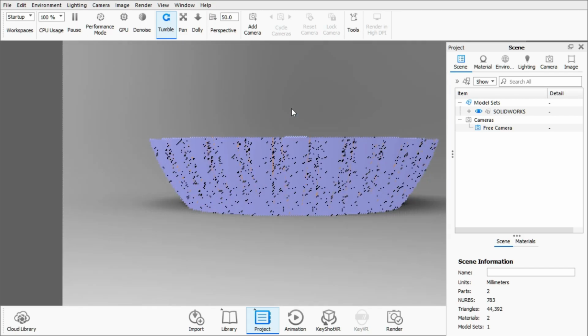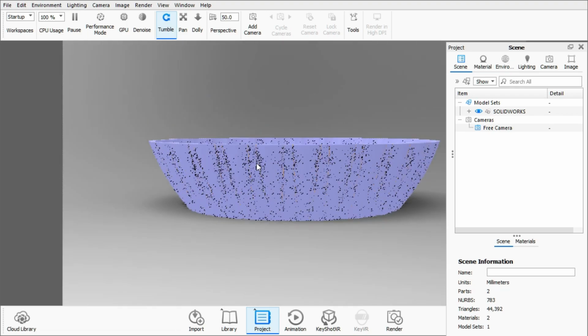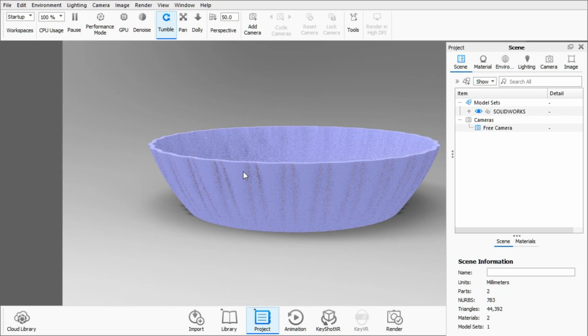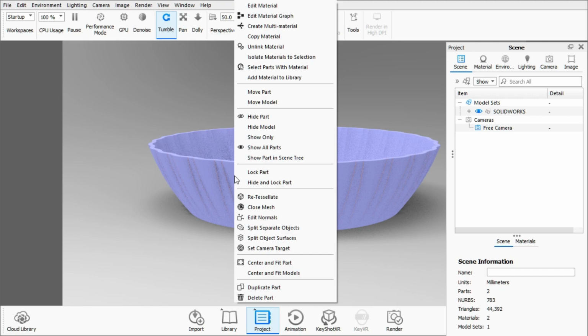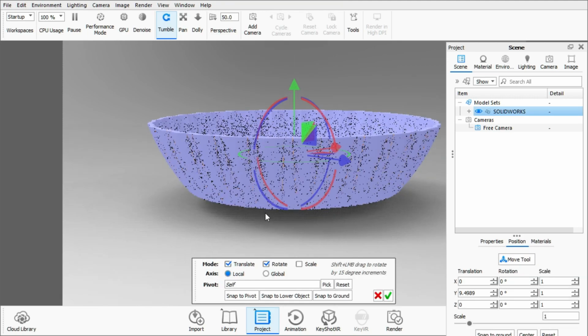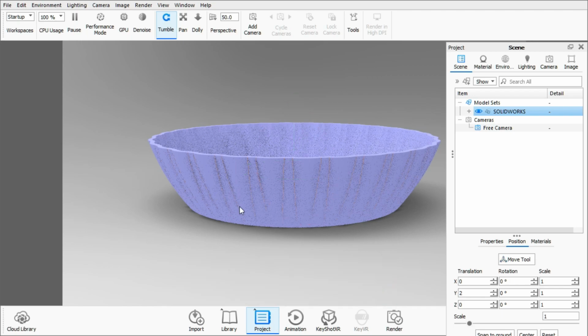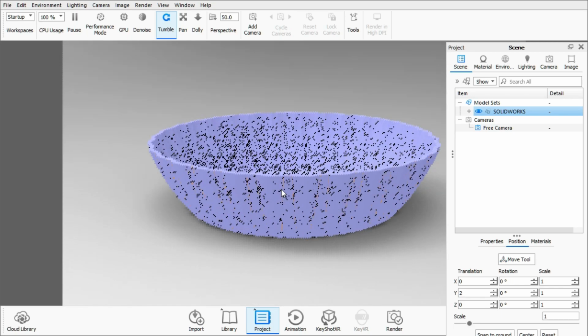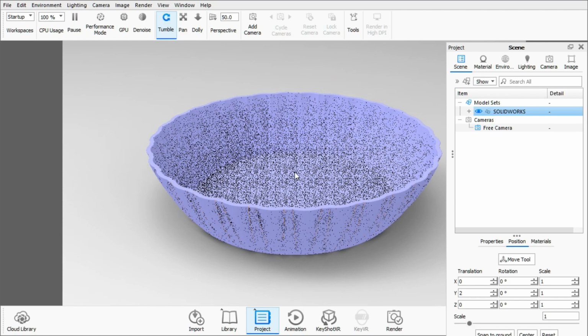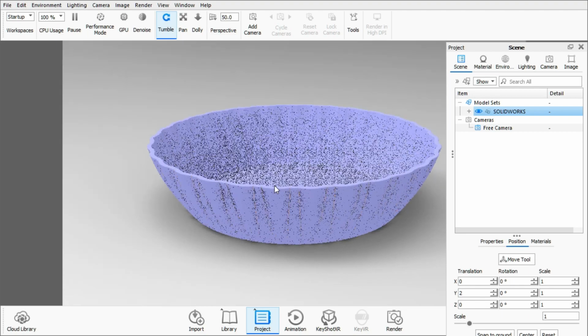And here you can see that the shadows are right at the bottom side, so I'll go to move model upside and snap to ground. Let's say if it's not snapping to ground, I'll check this box, snap to ground. Okay, now it is snapped. It is not always snapped, so you have to make this right.